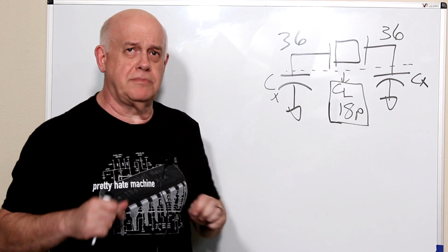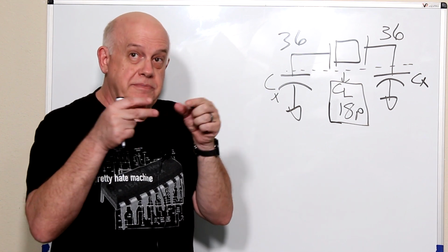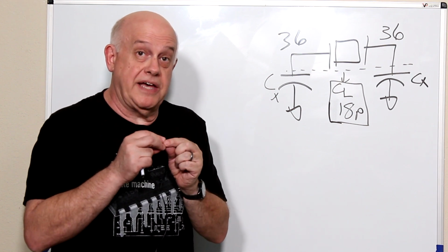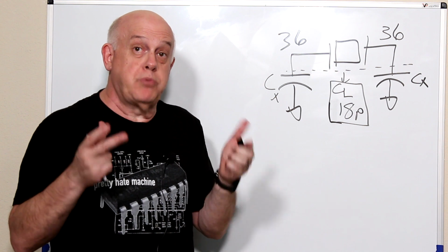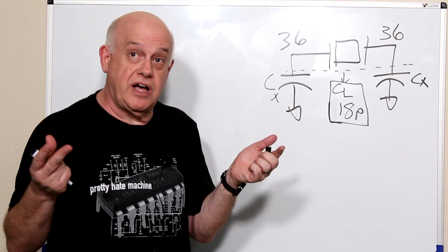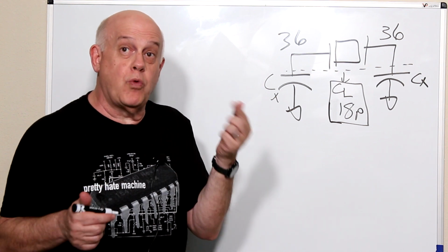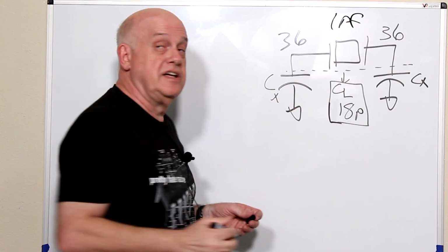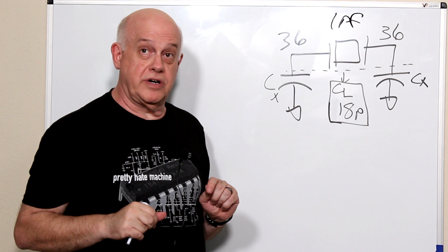I'll put them this far apart on my board. No, you have to make everything tight and close to minimize the stray capacitance. And for most boards that are designed fairly well, that's on the order of 1 picofarad. So there's 1 picofarad of stray capacitance on the board.